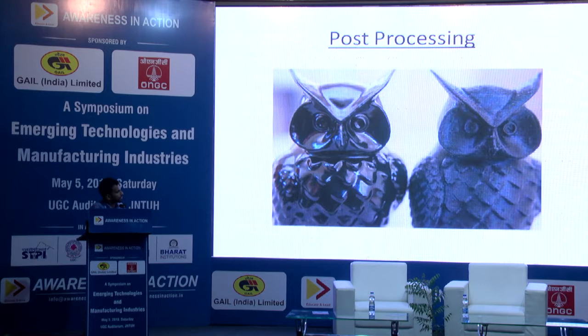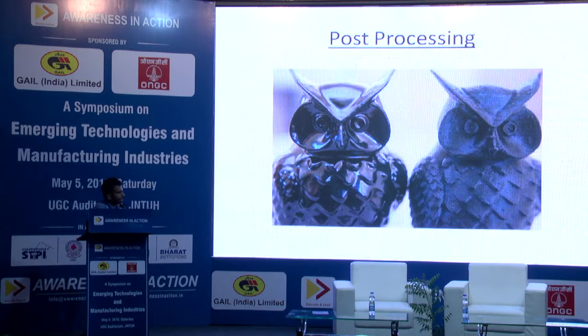There are a lot of post-processing methods. There are manual methods where you can use different grades of sandpaper and just keep rubbing, but again, it takes a lot of time. There is something called an acetone bath. If that particular part was printed in ABS, acetone only reacts with ABS, not with PLA or nylon or any other plastics. So you print the part, then keep it on a heated bed and maintain a temperature of 100 to 110 degrees Celsius. You pour droplets of acetone around it.